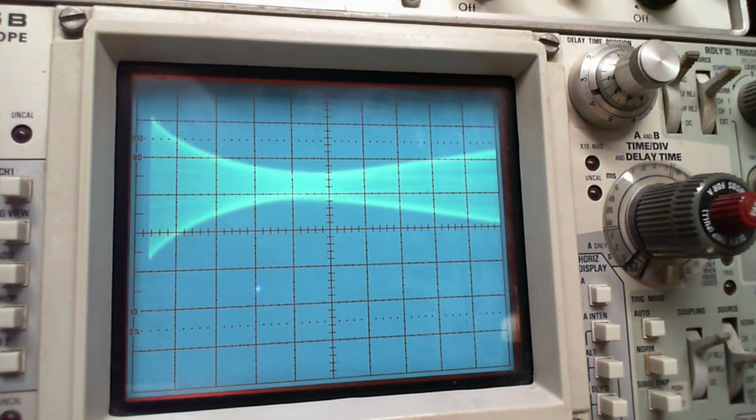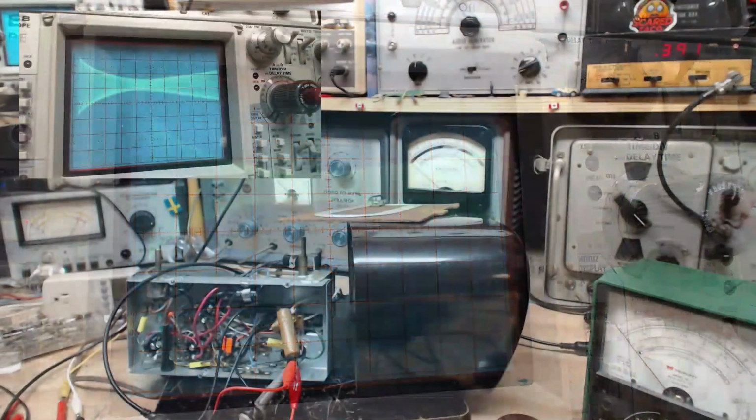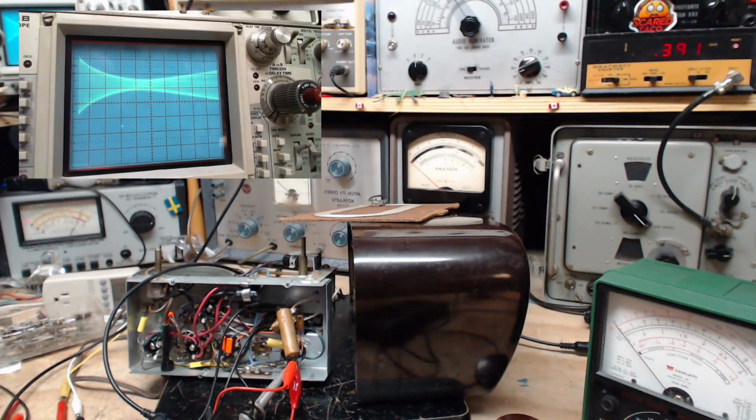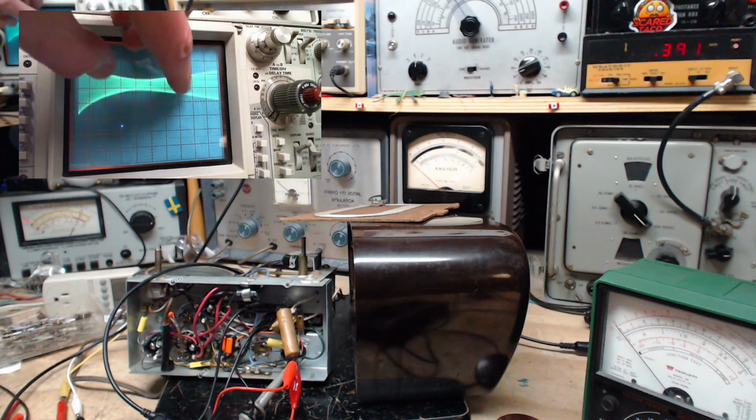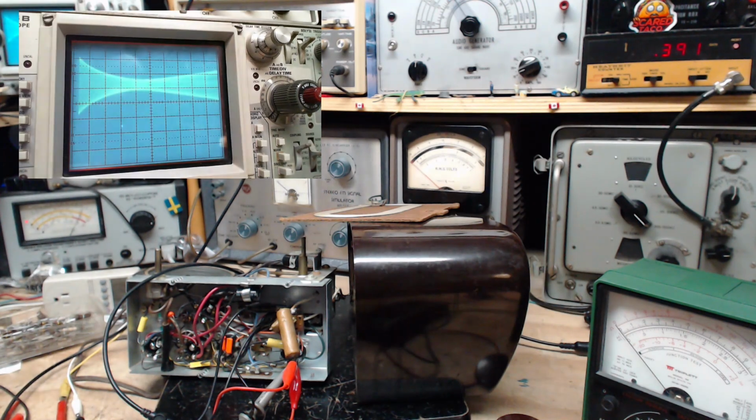What is the frequency, Kenneth? 391. So that's supposed to be 455. If this test is done correctly, if this is working the way I think it is, then we've shown that this capacitor is resonating way off of 455, down at 391, which is useless to the radio. We can see that the resonance for 455 was up around here somewhere, and you've got this much reactance, whatever that means. I mean, this is not a calibrated test by any means.